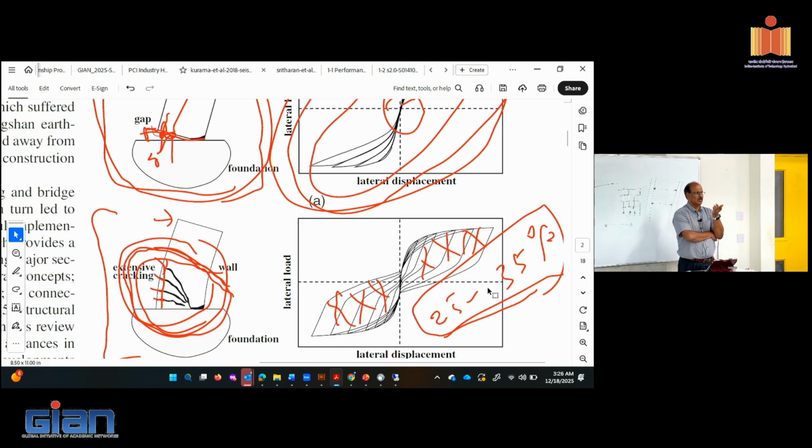Even steel structures. So the Northridge earthquake, when the Northridge earthquake happened, concrete buildings did okay. Bridges performed poorly. Some of the bridges we knew were likely to get damaged in an earthquake. They were upgrading them, but the earthquake came along before they finished the upgrading. So some of the structures experienced pretty significant damage. Precast performed poorly, but steel structures appeared to have worked out really well, and the steel industry kind of celebrated the direction to go with steel structures.